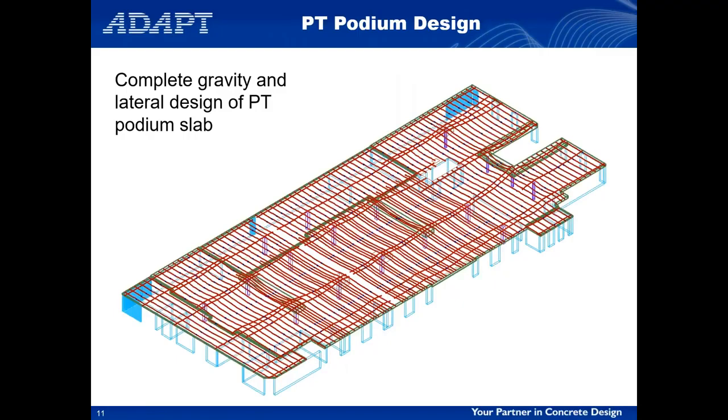Once we have our loads defined on the podium, the design of the podium itself is no different than any Floor Pro analysis and design that you've gone through. You're running it in single level mode, laying out your post-tensioning, laying out your support lines and everything else. One question does come up, and this just crossed my mind.